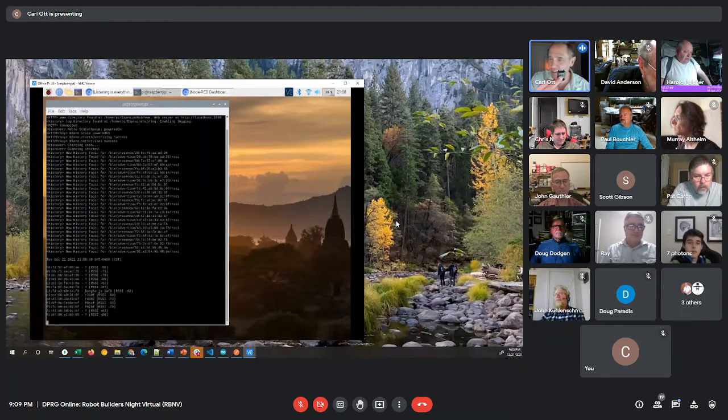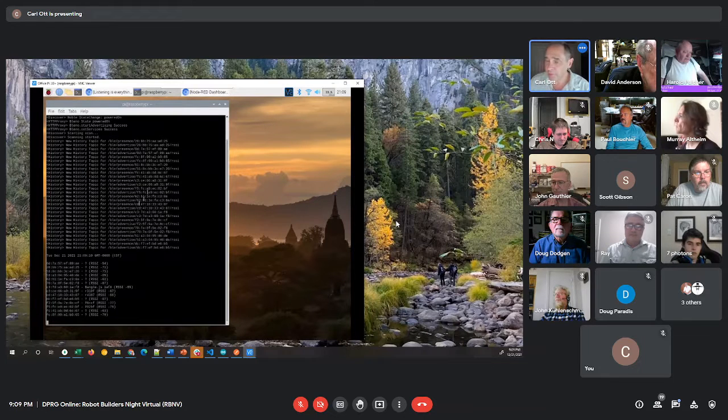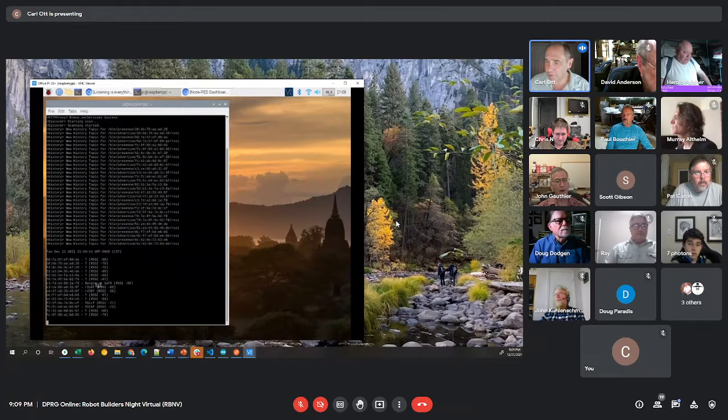If these guys send a value, they can send it by a BLE packet, like a heart rate monitor or whatever, and then this gateway would take that signal from one of these BLE dongles or BLE beacons and translate it into an MQTT message so that it could be picked up and used anywhere else.